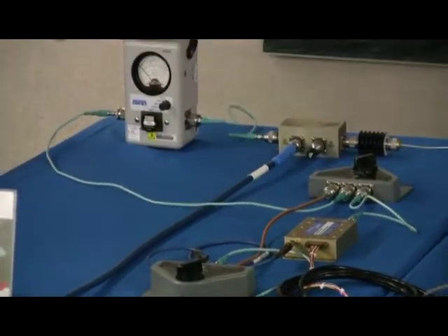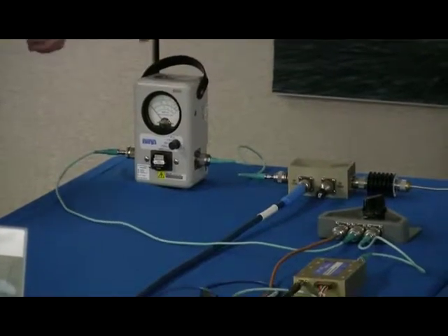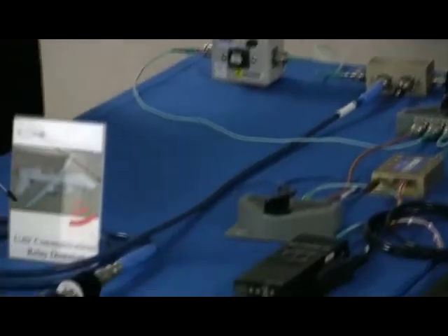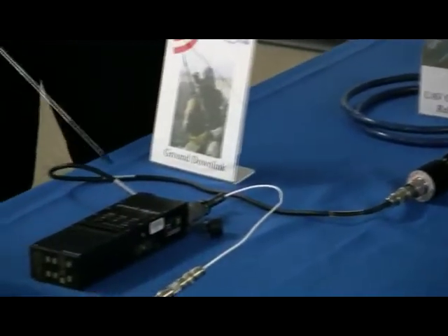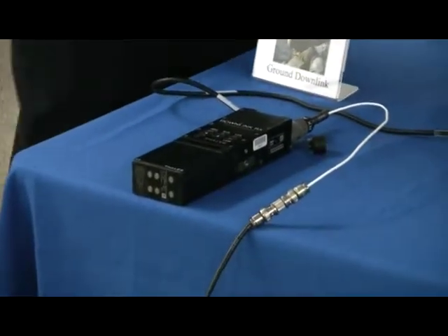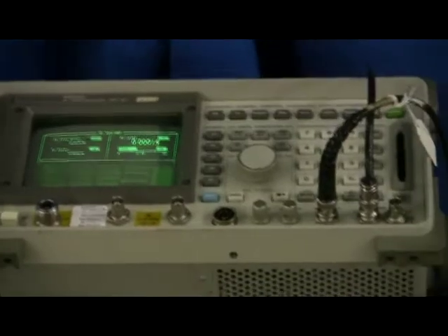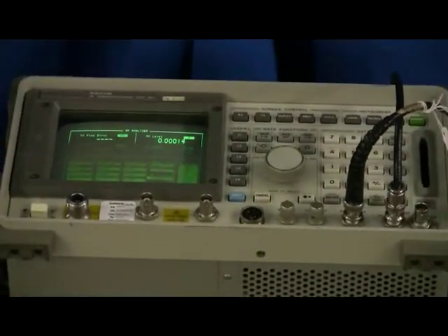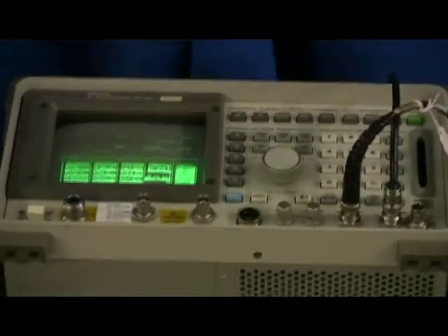The output signal comes through this power meter. We should see nominally 5 watts of output power. That signal couples through this attenuator network and goes to the downlink receiver. The output of the downlink receiver, which is audio, is fed into the communications analyzer to determine the quality of that audio. And again, we're looking to get an audio quality, a SINAD, in excess of 12 dB.